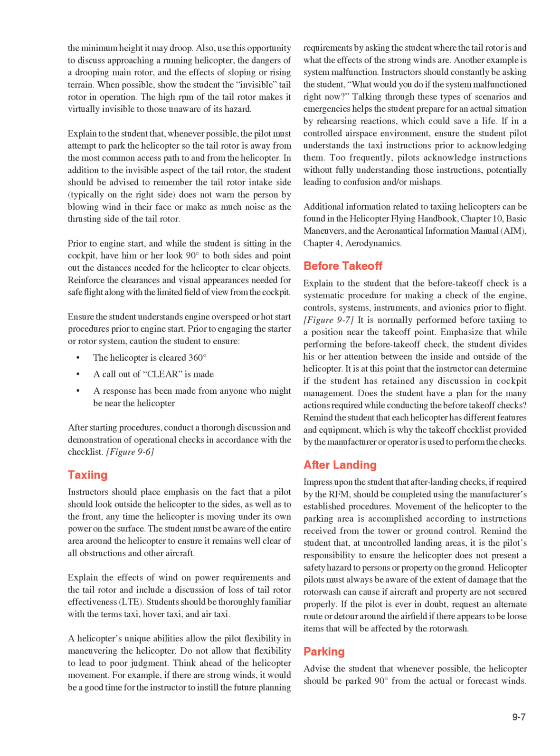Movement of the helicopter to the parking area is accomplished according to instructions received from the tower or ground control. Remind the student that, at uncontrolled landing areas, it is the pilot's responsibility to ensure the helicopter does not present a safety hazard to persons or property on the ground. Helicopter pilots must always be aware of the extent of damage that the rotor wash can cause if aircraft and property are not secured properly.